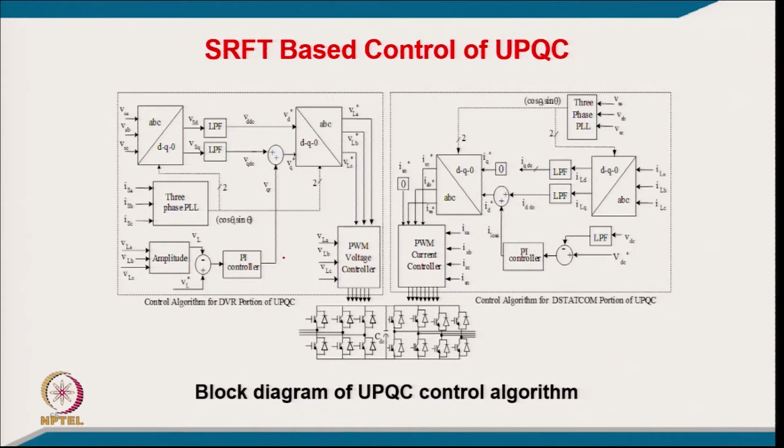So, that gives us the voltage component corresponding to the reactive power for voltage regulation or control, and VD and VQ, again with cos theta and sin theta, we convert to the load voltage, that is the regulated voltage, and we have a feedback voltage. So, that gives the gating signal for the series compensator or the DVR devices, which are part of the inverter.